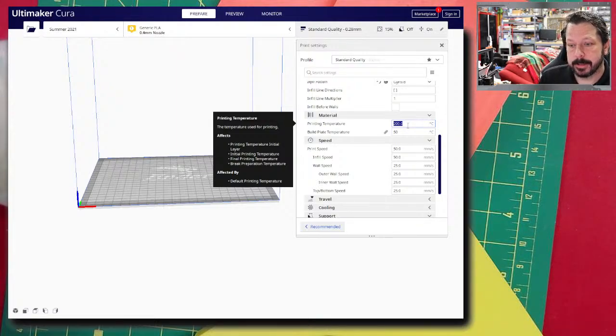In general, the cooler you can print, the better the surface finish on the outside is going to look, because there's not as many chances for drips and sags and runs, I'm thinking of paint right there, but for blobs on the outside, and strings and things like that, because the material is not as hot and it can cool faster.